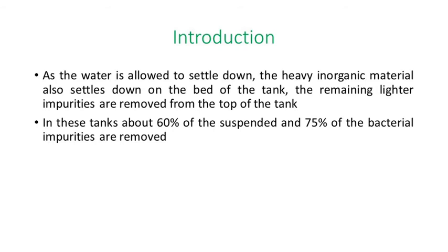In the sedimentation process, it removes about 60% of suspended solids and 75% of bacterial impurities. So almost 50% of the load of that water is going to be removed in the plain sedimentation process. Almost 60% of solids and 75% of bacteria are removed in this process of sedimentation.